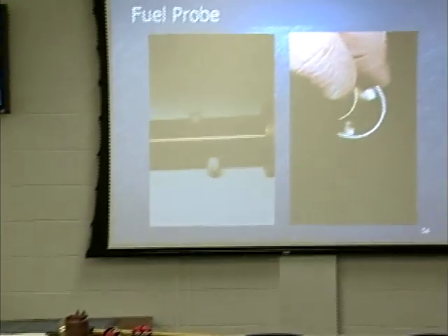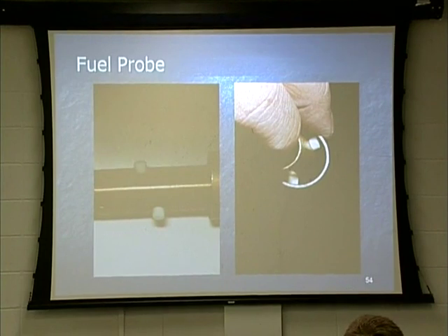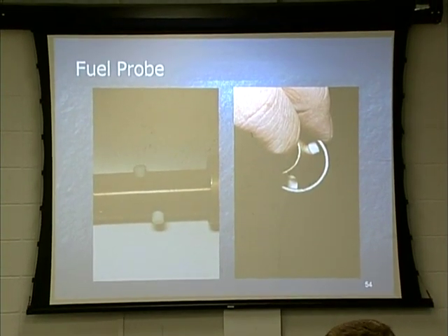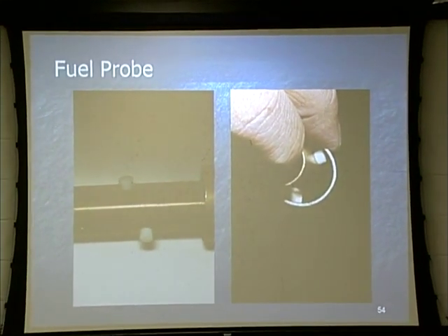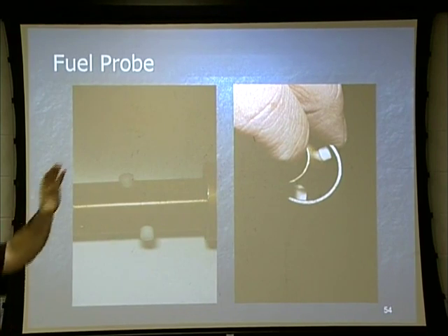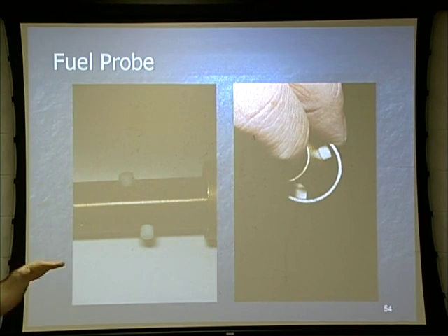Now, we said the main tanks have how many of those probes? 3. Now, again, the signal goes from the aft probe to the center probe to the forward probe. From the forward probe, it goes up to the selector and to the indicator. And it's going to send the average of all 3 probes. But the center one, that's the low level. Why don't they take all the low level of those probes as well?